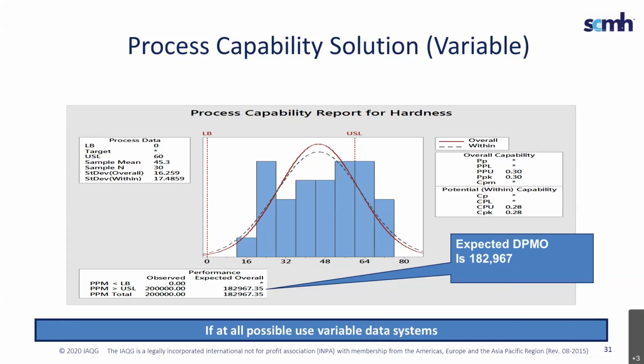Yeah, so that's got to be a very specific question with the customer. Again, 100% sampling, and if you're still not at the minimum requirements from your customer, then we'll have to figure out a way. Some customers may allow similar processes, similar to FAI. If you've got the same product with the same features of the same process, you might be able to use that type of similarity for your process capability. But again, these are typical questions for your customer. I've seen that, but you always have to ask your customer what's acceptable as far as similarity goes.